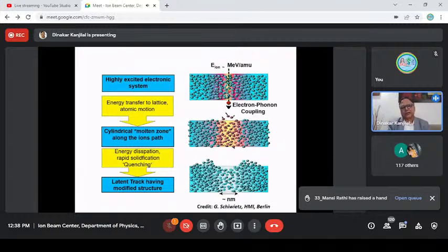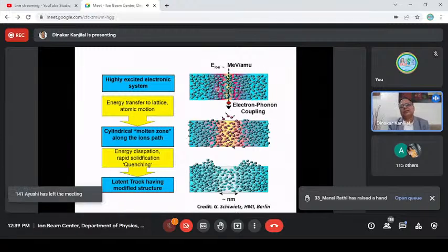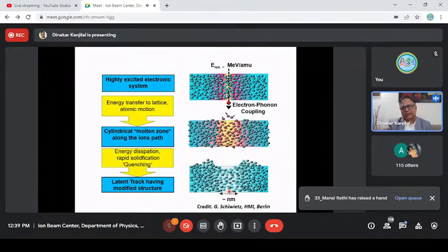So it becomes highly charged as well as highly hot. Some of the heat transfers to the lattice side. So both Coulombic interactions and thermal spike are omnipresent. Depending on the conductivity of the material, if heat transfers fast, then more Coulombic interaction takes place. If it is, say, an insulator, then whatever heat cannot pass becomes superheated and gets frozen into a state. It is due mainly to the thermal spike. So there are two major processes by which this energy finally gets settled in the material.